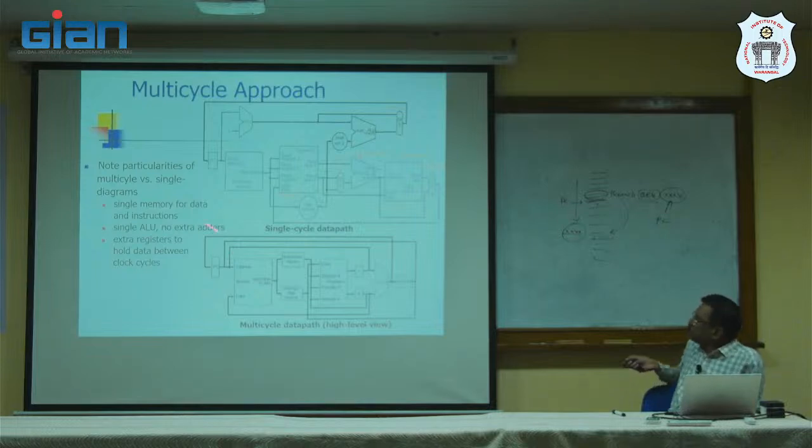Okay, so the components, we can reuse the components. We need not require multiple components. See, one adder here is the ALU. So two extra adders are there. One adder for address calculation, this is for jump address calculation, and this is for the actual ALU. But that can be eliminated. Some of the components we can remove and we can put only one ALU.